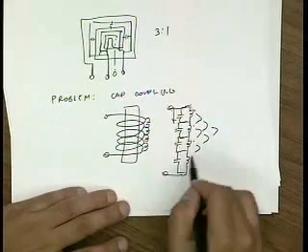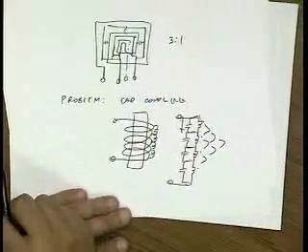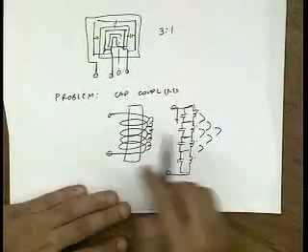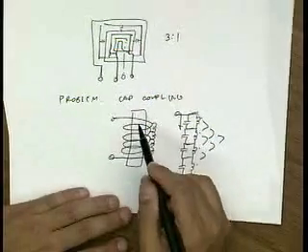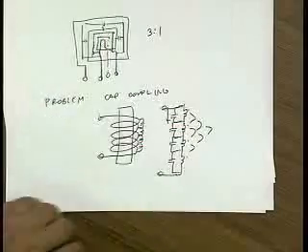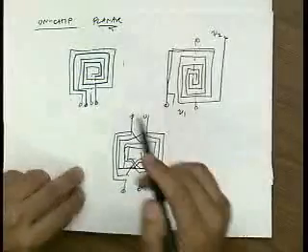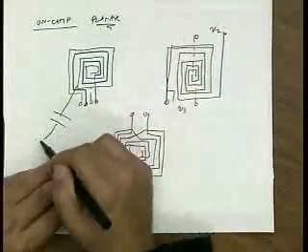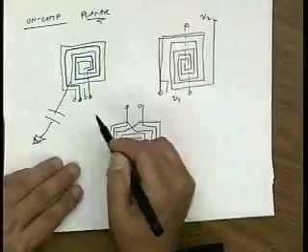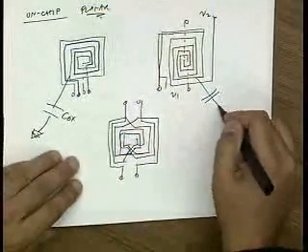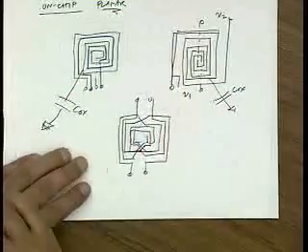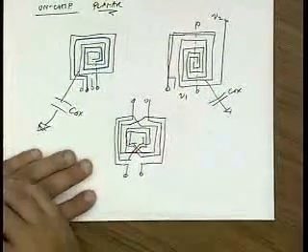So ultimately, all inductors self-resonate. Okay? Now for off-chip kinds of inductors, it's usually the winding inductance that dominates. For on-chip structures, there's a huge capacitance to ground through the substrate. Similar thing here. And so this will ultimately lead to self-resonance in the structure.